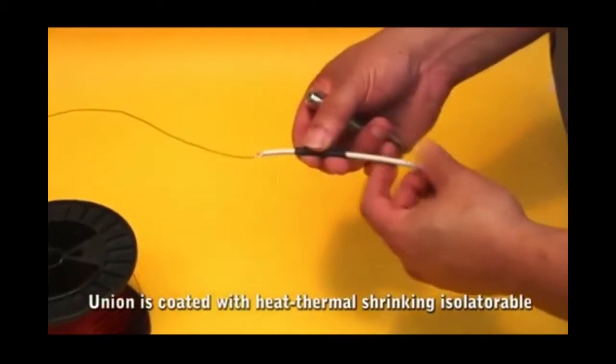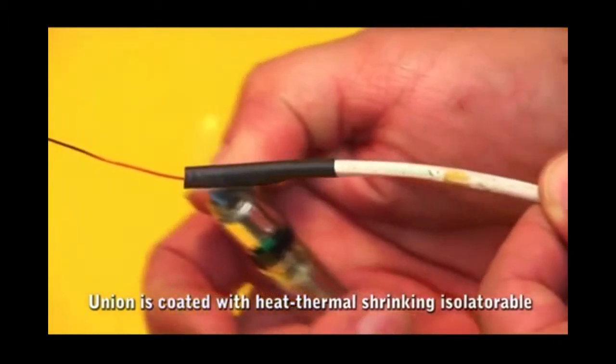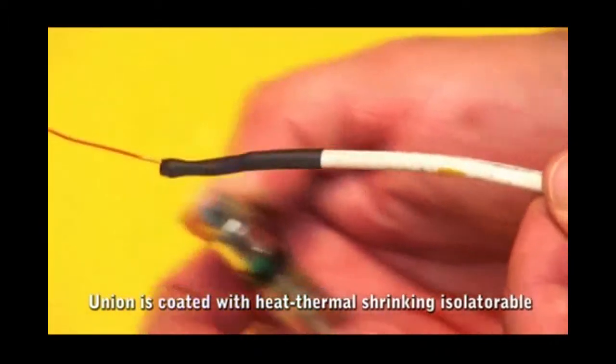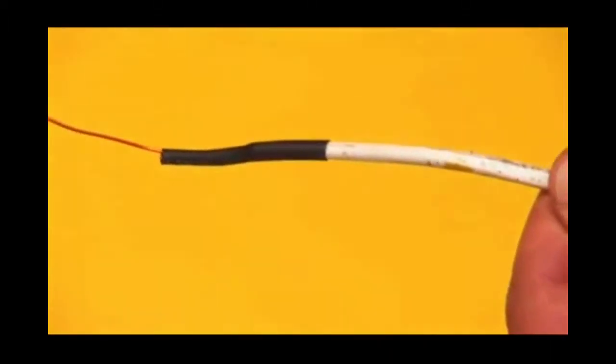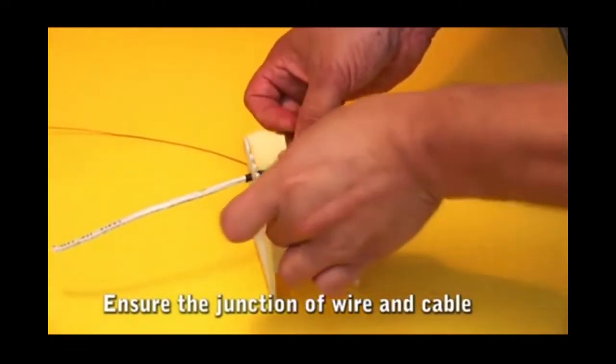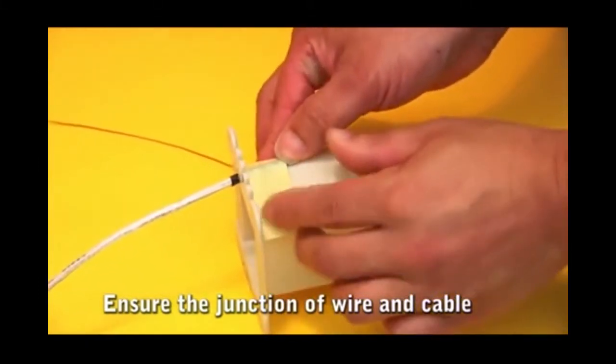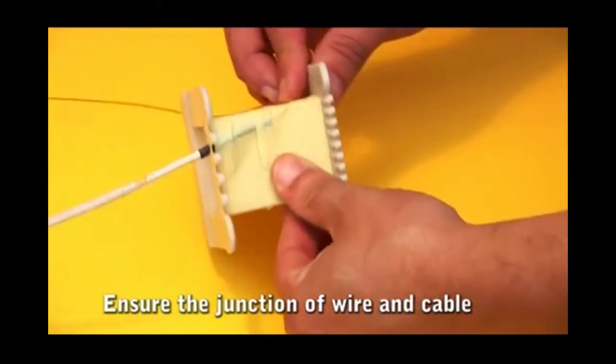Used 3 mm thermal shrinking insulator to insulate the joint. This heat-shrink insulator takes the form of what it covers. Insert the wire through the hole. The wire is secure, leaving the union within the mold. Secure the wire with masking tape.